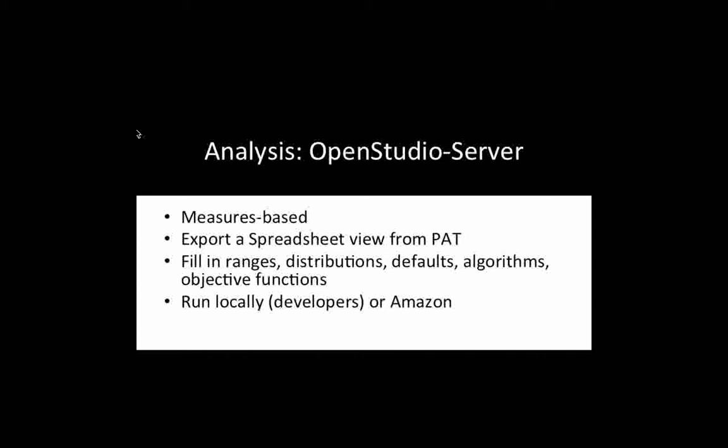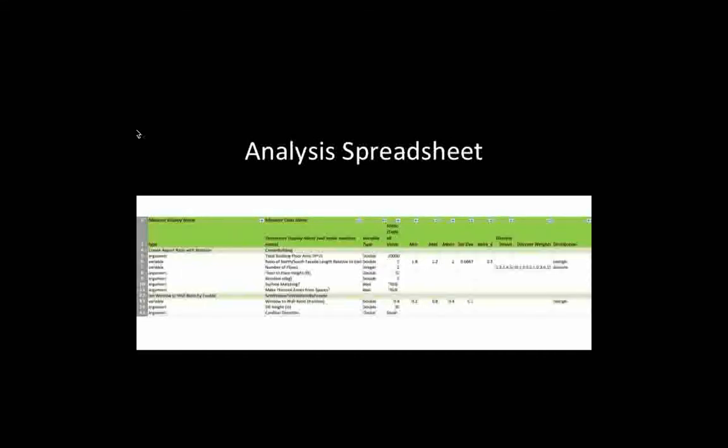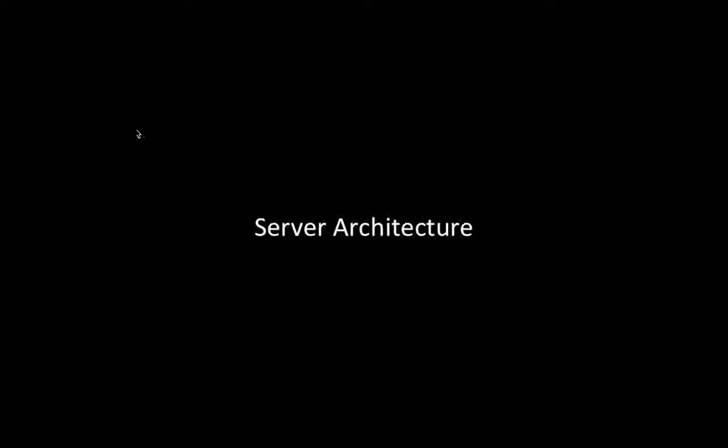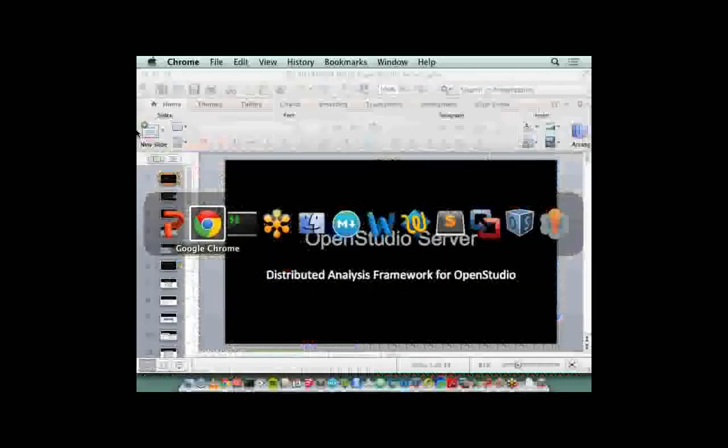So OpenStudio Server is sort of like the next step in this evolution. It's all measures based, but the idea is that you start with a spreadsheet where you have a seed model, and in the spreadsheet you fill out some fields, which looks like this, where you stack up your measures in here. You set in your different parameters. This whole problem is then exported to the cloud. Again, it's replicable. I'm not going to talk about the server architecture, and I'm going to really quickly just go over to